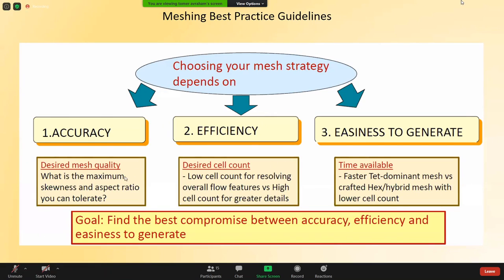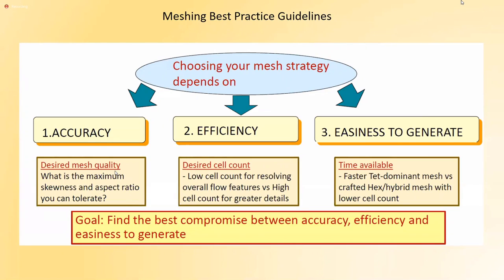Okay, so desired mesh quality. Mesh quality is very important, especially in the boundary layer, but not only in the boundary layer. We'll see some meshes that would astound you that are better for some kinds of applications than others. But especially in the boundary layer, we want our inflation, or let's say I call it orthogonal layers.